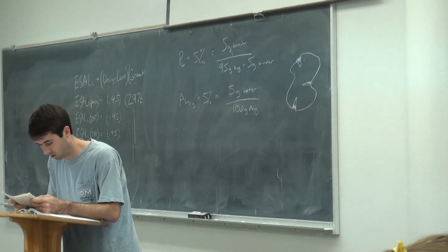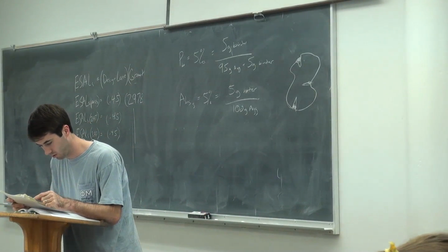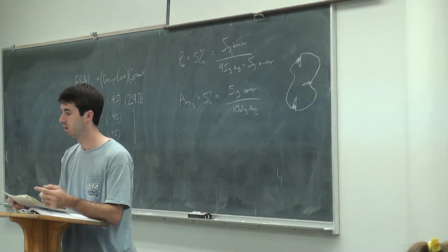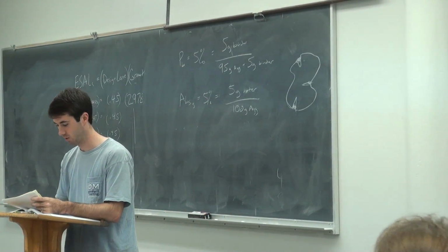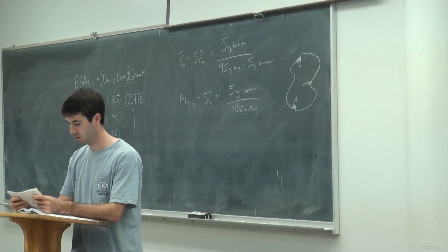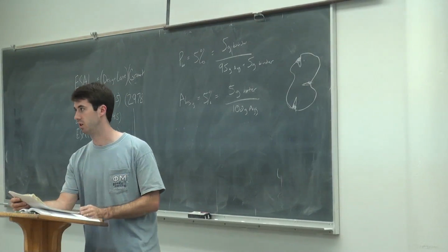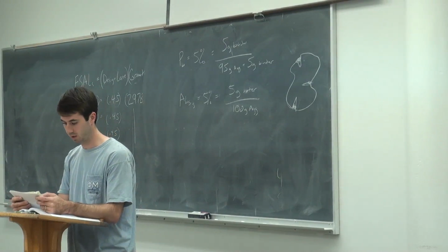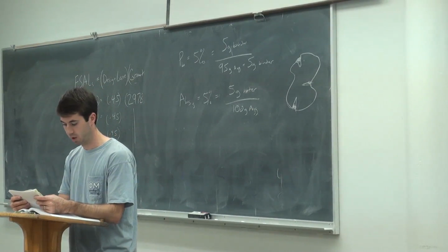So when they go to the graded binder, they're going to run several tests on it. They're going to run flashpoint, which is just a safety thing. They'll run it at this 230C that you see here. It goes all the way across that chart, and it just has to meet that. That's just a safety spec, basically, to make sure it's not going to blow up on anybody.